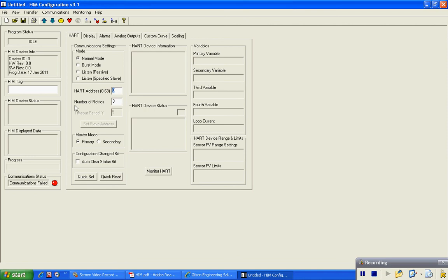In normal mode, the HIM polls the HART loop for a transmitter, then polls the HART instrument twice per second, requesting the current process status and the HART instrument's diagnostic status. The HART instrument responds with the requested data. In burst mode, the monitored HART instrument is programmed to continuously transmit its process variable and health status. The HIM samples the continuous HART data 3 times per second.